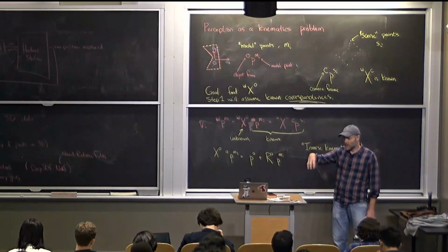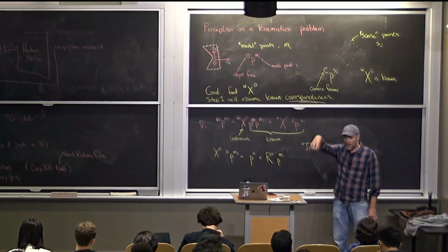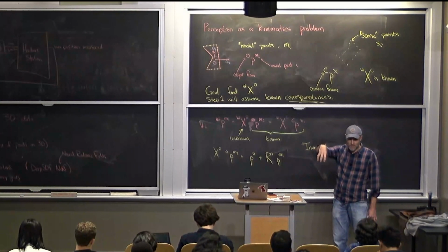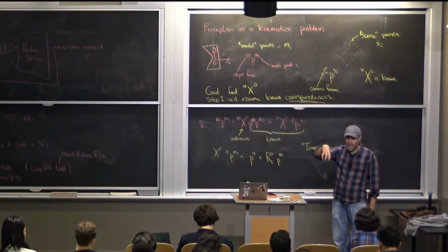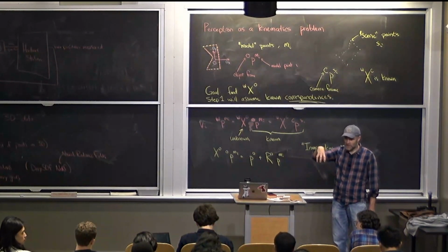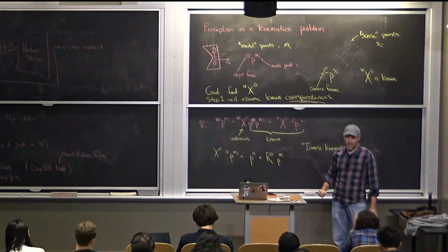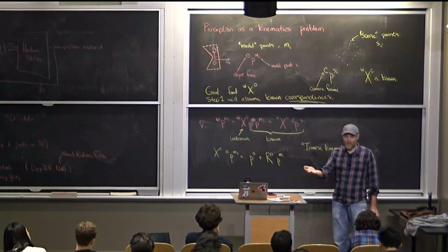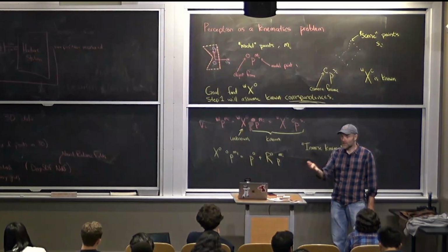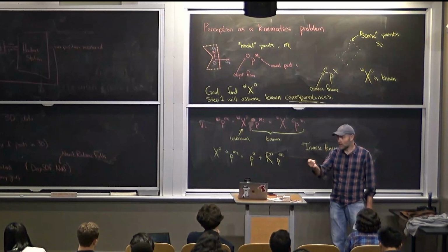I think that's right. So he says you don't have the ground truth, right? Effectively, the magic that happens in the robot case is that you know the initial conditions, and you want to change those initial conditions. So you have an initial Q, and you're making small changes to that, so you have a place to linearize around. In perception, at least once you have to wake up and figure out where the objects are. You don't have an initial guess, unless someone gives you a good one, and then you could be in the land of differential inverse kinematics.